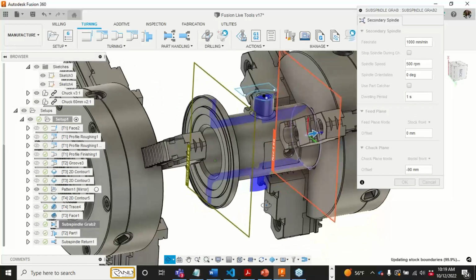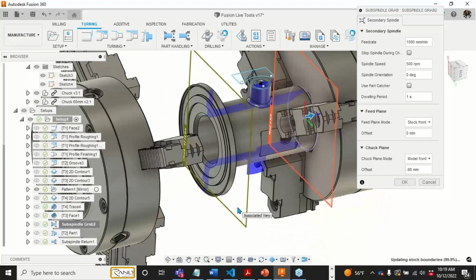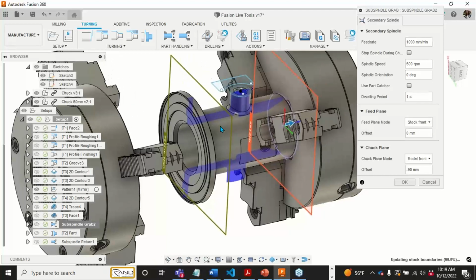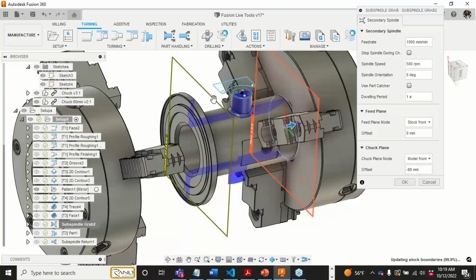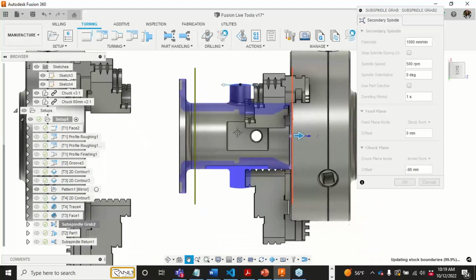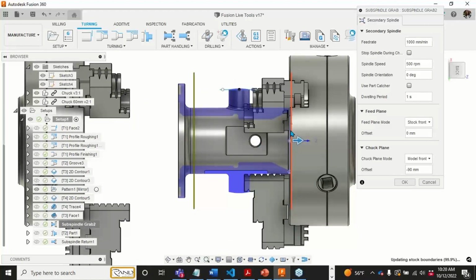So there lies the problem of some of the turn mill operations. How do I machine this? Well, I'd probably machine all this complex stuff on this side, and then I would clamp it on that side as well. So this first line here is how deep I want this chuck to go as it's clamping onto my part. And again, the model's not going to do it because we can't simulate it yet anyway. And then this line right here is where it starts feeding in.